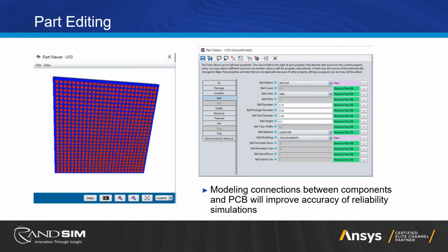And so if you take your design process from manufacturer A, and then you switch your part to manufacturer B because you have the shortage in manufacturer A, you want to make sure that if there are some changes in the land pattern or the ball size associated with that other part, you want to make sure that you're capturing that.